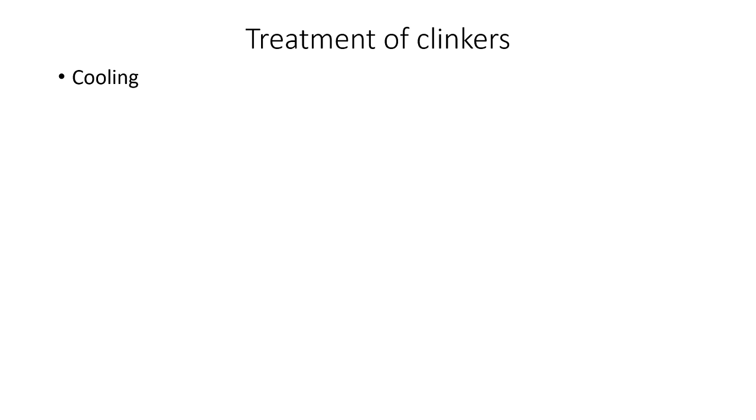So the cooling air blows the dust from the clinker. Okay, so this cannot be allowed to escape into the atmosphere, which may cause air pollution. So the dust is trapped in a settling chamber, which is returned to the kiln. This settling chamber is there at the beginning of the kiln.